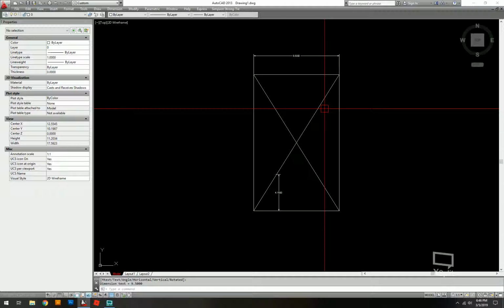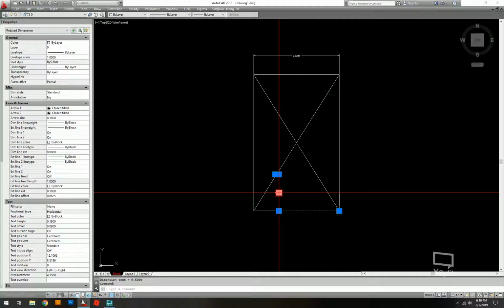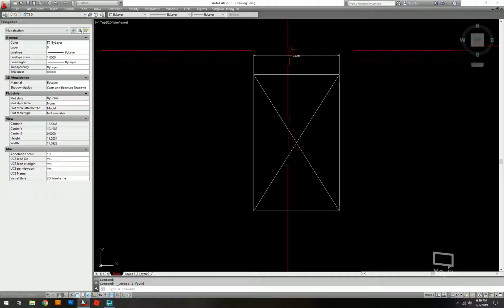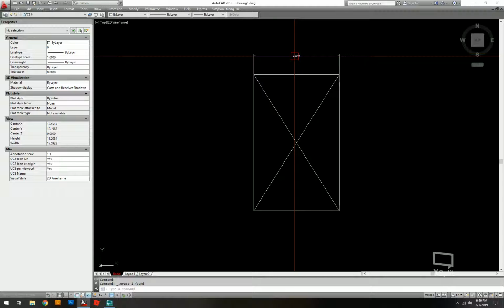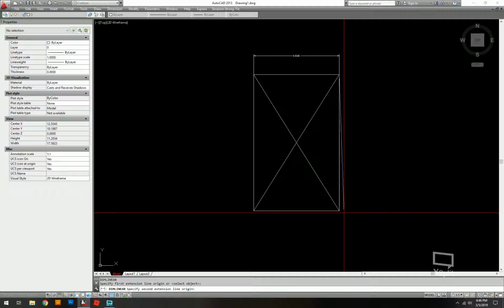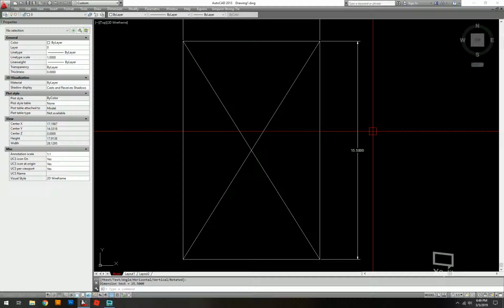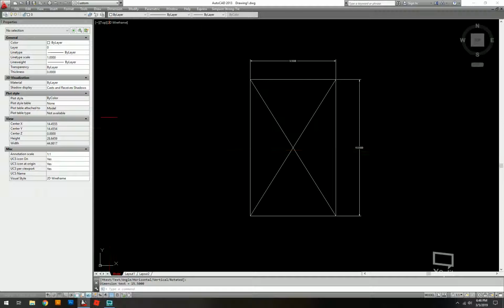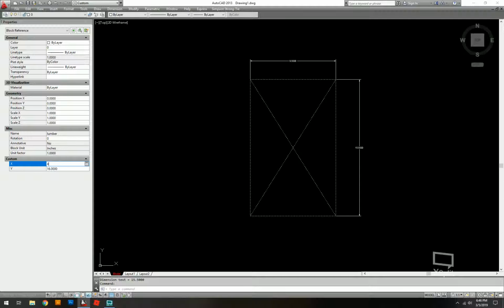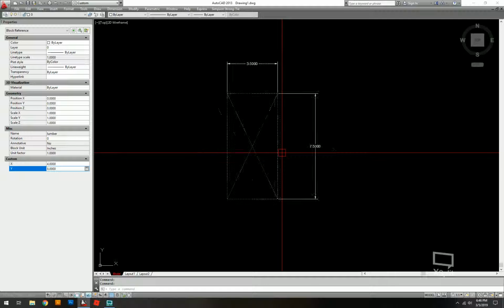Basically on the newer versions, and especially in AutoCAD 2019, I know for sure, there's a plus sign in the toolbar down here, and if you click it, you can see that when you break the dimensions, there's a little yellow box with an exclamation point in it. It's basically telling you that you broke it. It's no longer associated with the 2 edges that you chose originally. If you click on the exclamation point, you can reassign it to those corners and do what we're doing right here, where we do endpoint and endpoint, and then it will reassociate to those corners. So when you select it and change whatever, it will go along with it.